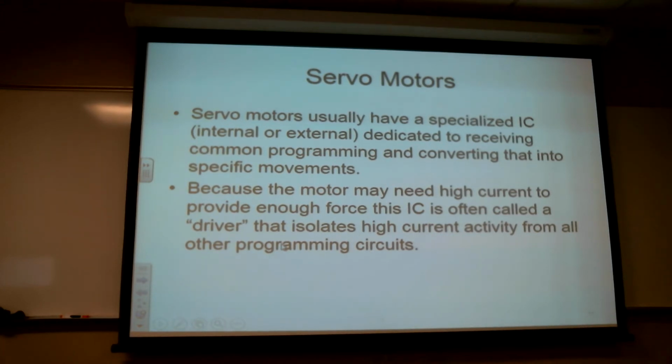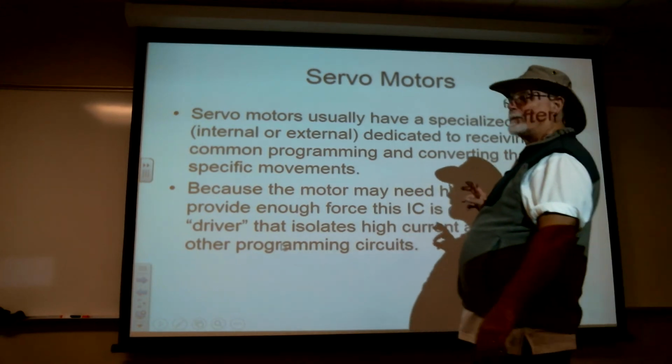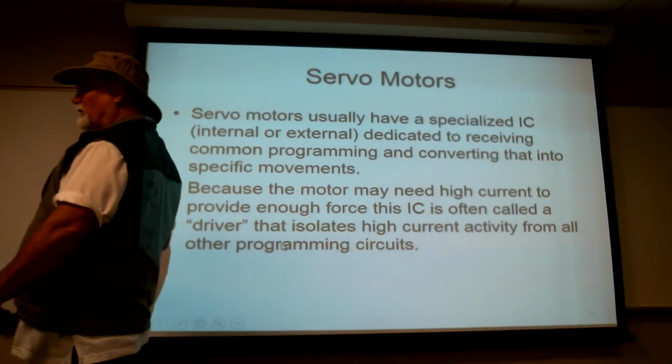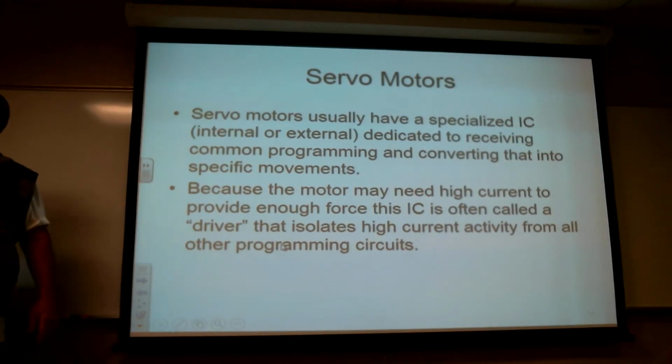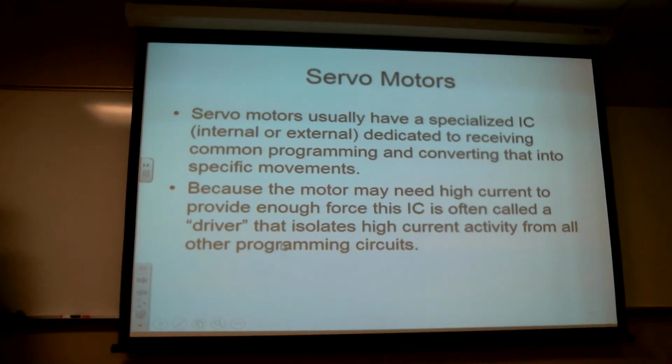The driver is physically going to turn off and on a variety of different transistors to get the motor to do what I just told it to do. So I'm going to have this little miniature computer that's dedicated to causing the servo to run, and that little computer is expecting to see some binary set of instructions.